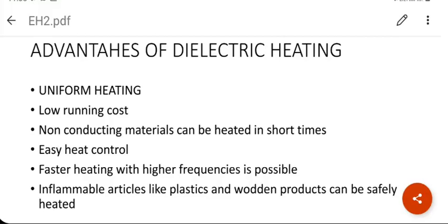But jewelers, the good jewelers, still set up the whole thing to condition the jewelry using dielectric heating, which makes it beautiful as well as long lasting. So, it's a financial call ultimately, whether to go for dielectric heating or not. Big industries usually go for it. Even the large furniture manufacturers always have dielectric heating at the end of their manufacturing process to make the furniture last longer and to make it look good cosmetically.